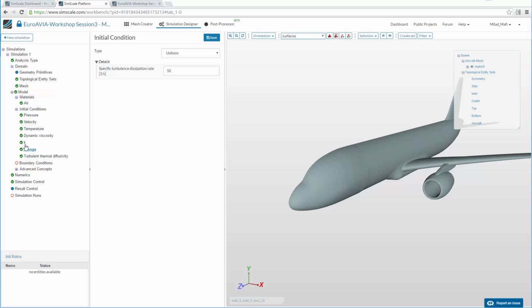But basically, you only need your Reynolds number, and out of the Reynolds number and some other parameters, you can calculate K and omega very easily yourself. And what is happening is that we use this as initialization for the whole field because this makes sense and will help to reach a fast convergence.